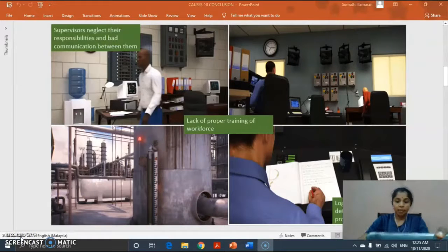Next, the night shift operator did not inform the day shift operator about the fault in the second safety alarm system before handing over the operation. He also failed to record the issue in the logbook. Then the day shift operator left the control room an hour early due to some family issues, and left a supervisor with a lack of proper training to operate the startup process. It is completely wrong that if he wants to leave the control room early due to some issues, he should have appointed a well-trained supervisor to operate the control room.